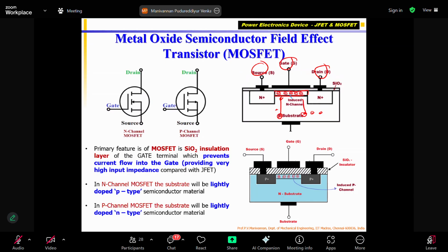So please note that these electrons are connecting the source terminal with the drain terminal. So this one provides a conducting path. The accumulated electrons below the gate terminal form a conducting path. So electrons from the source can start moving through this to this one, and basically you are going to connect a voltage source like this.